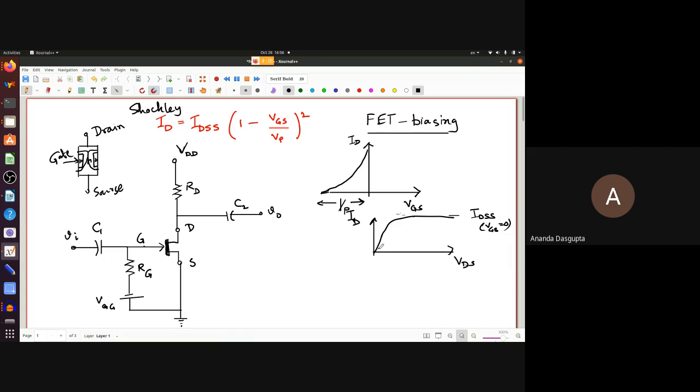And then if you put in negative VGS, which is what you are supposed to do, you're supposed to always use the junction field effect transistor in a reverse bias mode. The gate to channel has to be reverse biased. So you either put VGS equal to 0, that also produces a reverse bias because of the drain to source voltage difference. But you can actually also put in extra reverse bias with VGS, and that's exactly what that formula is telling you. If you put in extra reverse bias, the ID at which it saturates, this ID, keeps on going down.